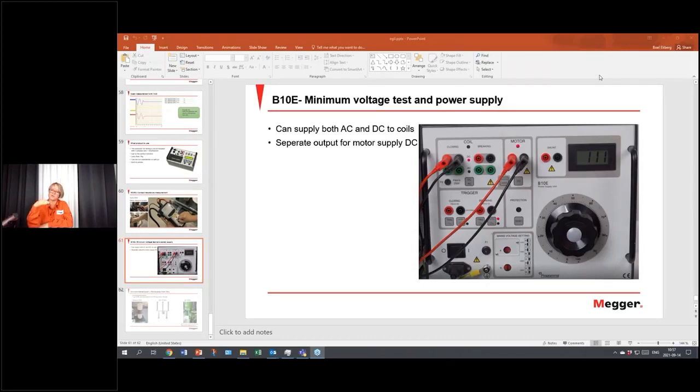Also, when you connect motion transducers, make sure that the circuit breaker is not charged. The spring should not be charged, because then you can get an operation by mistake and damage your hands, because there is very strong power in those springs. So that was just a little caution message. Take care of yourselves when doing these kinds of measurements. Think twice, right?